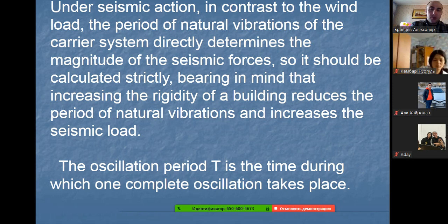Combinations of the loads. An important thing is to take into account not only the loads of the building separately, but also combinations of loads, like seismic loads and dead loads, seismic load and snow load, seismic load and other statical loads, and so on.